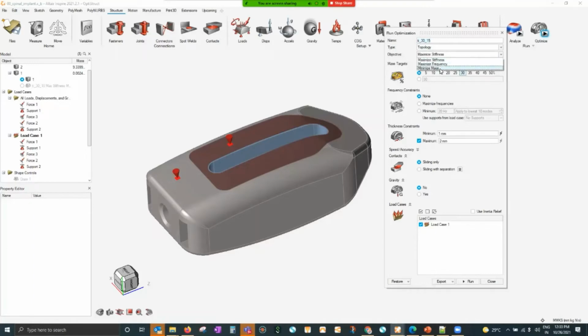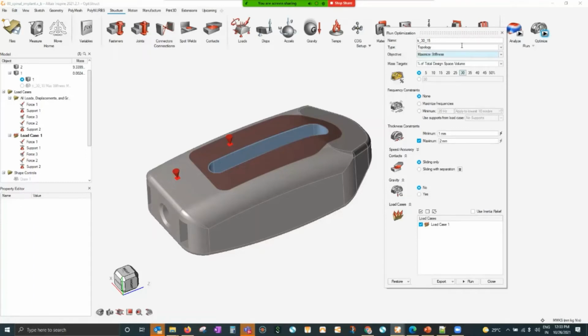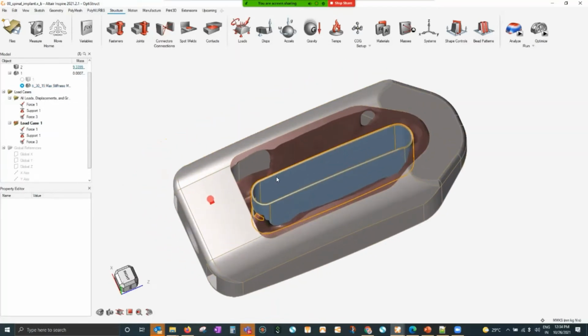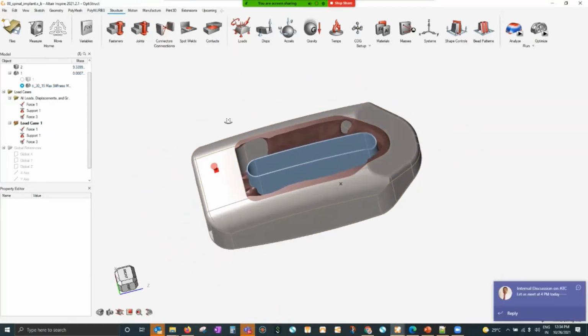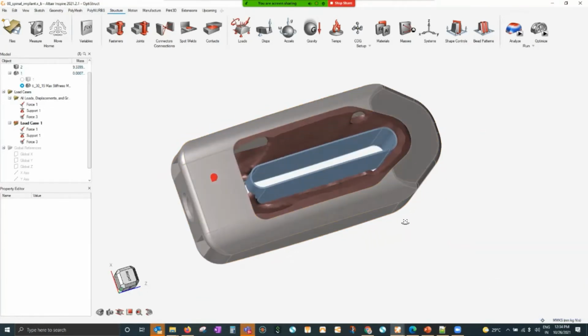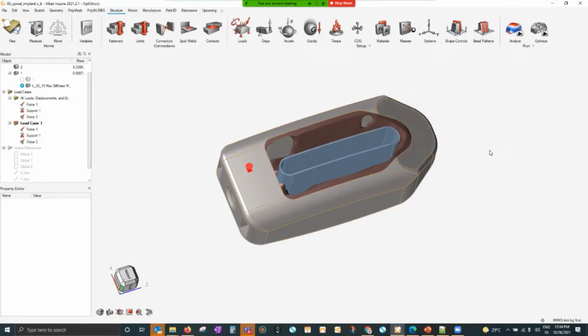If you go to minimize mass, here you are actually giving a factor of safety target, right? So both ways are there, but since we have done minimized stiffness over here, we have to do a secondary confirmation that this 30% whatever we have removed is sufficient, or we are not creating large stress or displacement in some areas beyond acceptable limit. How to check that? Again, it is very easy.